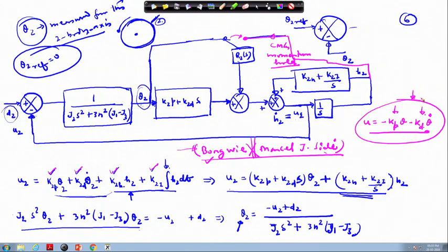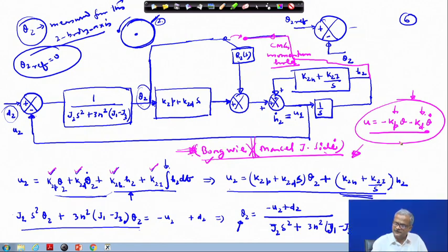Okay. But I will do that one case for the magnetic attitude control, which needs little extensive calculation also, but I will do that. This part you can look into the book by Wie and Marshall J. Sidi if you are interested in further simulating the satellite motion. You want to launch your own satellite for your institute. So, go through this part and you can do the local control, but if you have to do the control in a wider sense, means for a larger value of theta and other variables, then you need to use the Lyapunov stability analysis and do the control design accordingly.